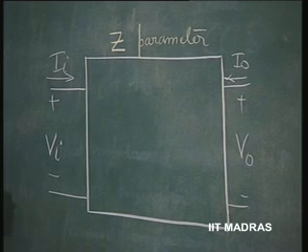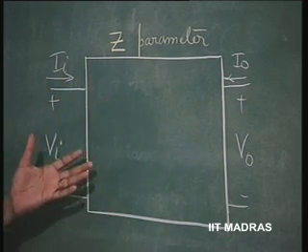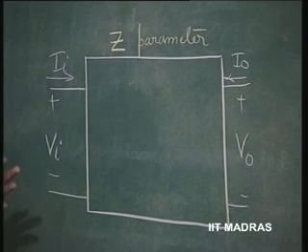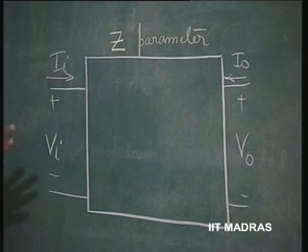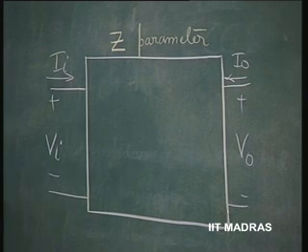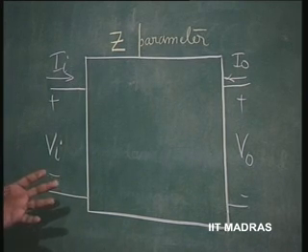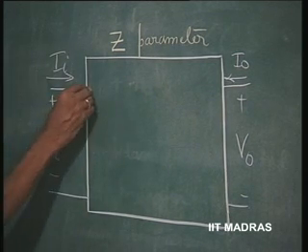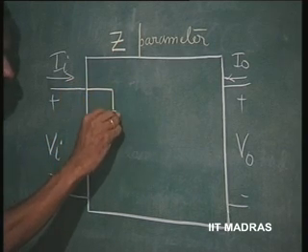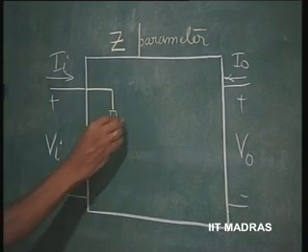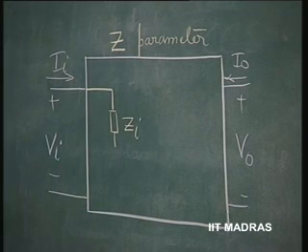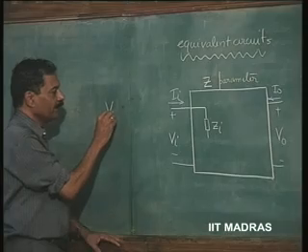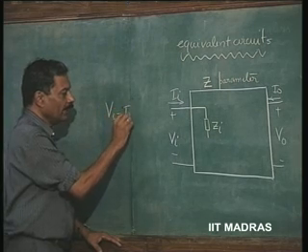Earlier, we put down these things in terms of equations, these independent variables and dependent variables, with the relationship as a linear relationship in terms of two equations. Instead, now the same thing will be represented as an equivalent source or an impedance or admittance accordingly. So, this is an impedance parameter. We have here at the input Zi, which is the self impedance. We have understood this Zi. Let us see what this equation is. Vi is equal to Ii into Zi.